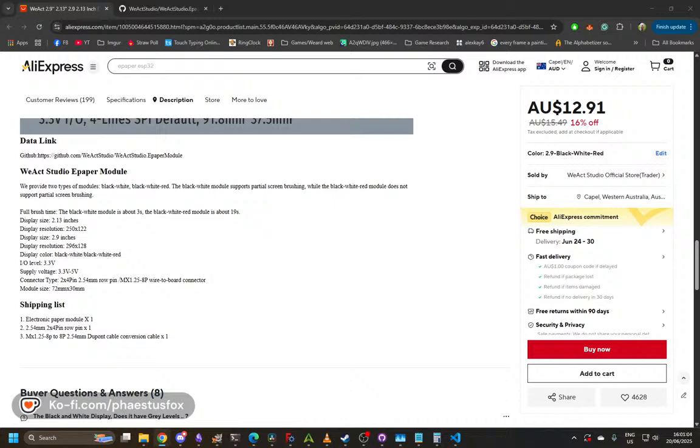Probably should. The issue isn't necessarily programming something to clear it. Obviously I just need to look up the library because I've done displays before, never e-paper, but I never got around to programming my Pico to just clear them. But the big issue, and the reason I'm not using an LCD, because I didn't realize LCDs were persistent. I assumed if you didn't power the LCD, the crystals would all relax and go back. But I guess it makes sense that if you twist the crystal, they would stay twisted until you swap the voltage back.